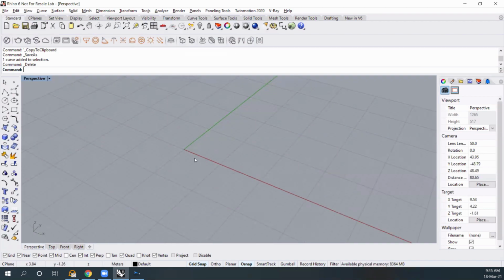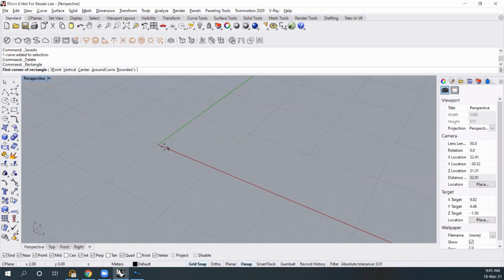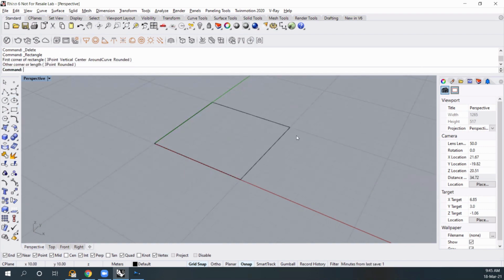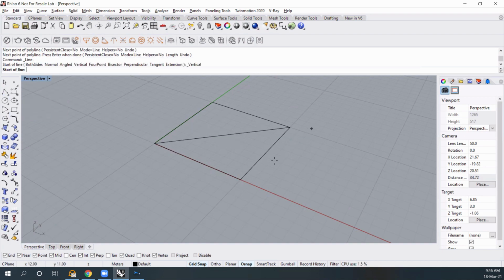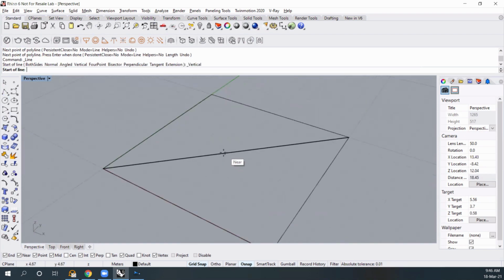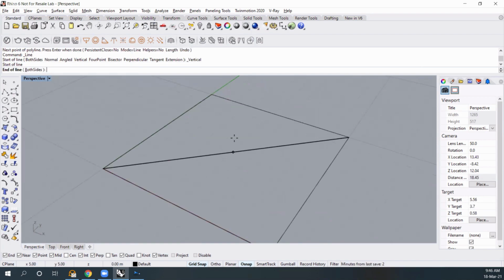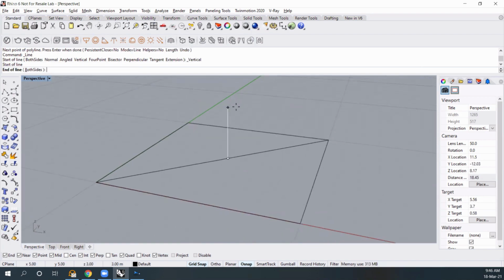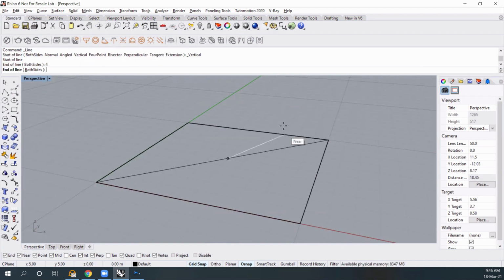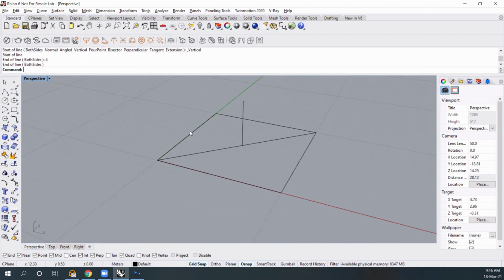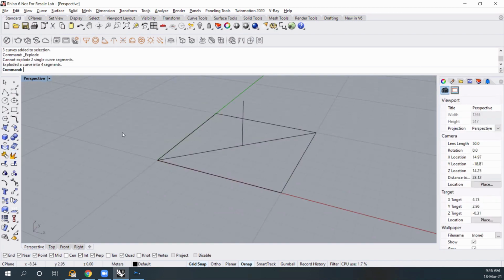Generally, you start from Rhino because it's easier. I can also draw inside X-Cube, but clearly it's faster here. I just want to generate a very simple rectangular base, a very simple conical shape. So I just input here. I have made a square 10 meters by 10 meters. And then I just make a vertical line of 4 meters. And that's it. Select everything, explode this.